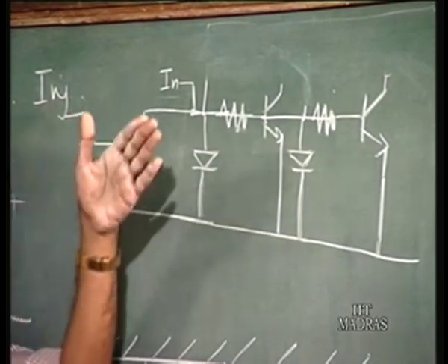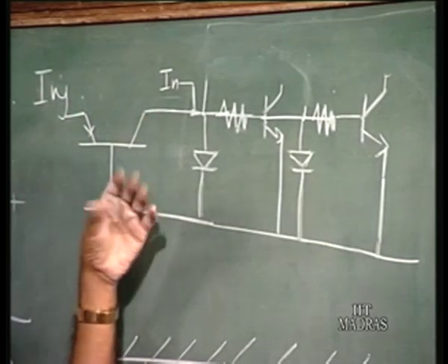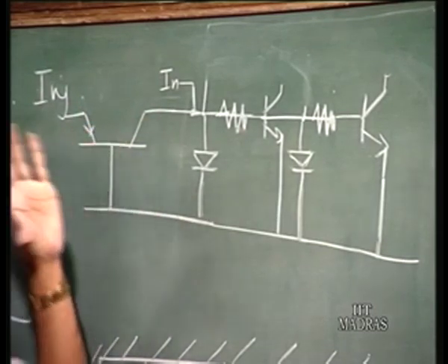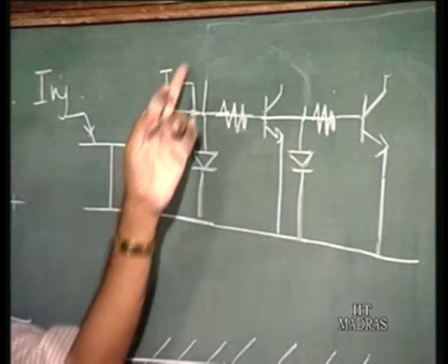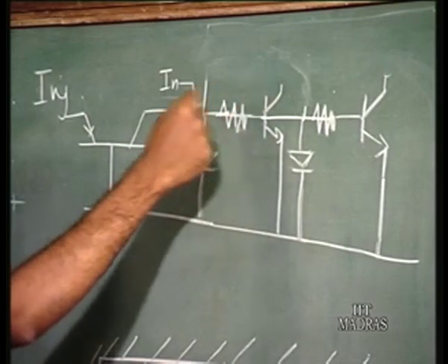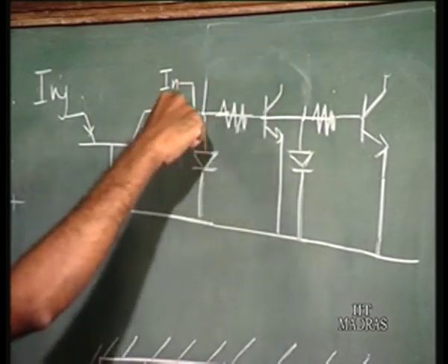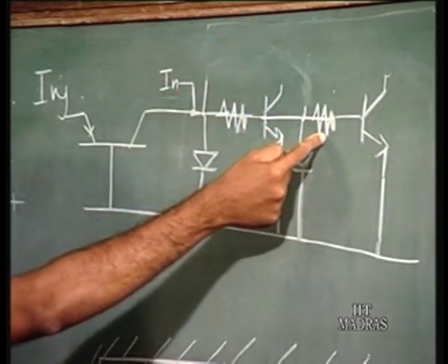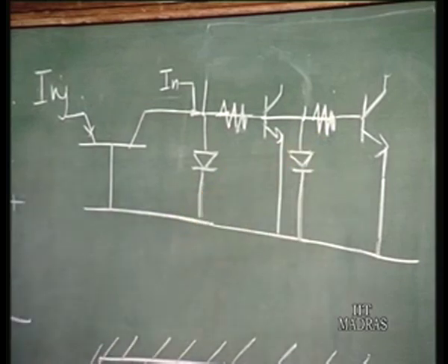In the rail region you do not have any collector diffusion, so the cross sectional areas are much larger, and those resistances were much lower. If they were there, the effective resistance for this would be less. So basically we have removed the low resistance path, so that is the problem.